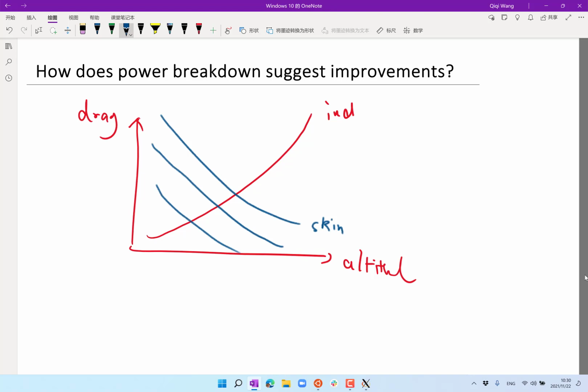There are two penalties. One is a weight penalty. So that's going to be the equation we supply to you. If you decrease the chord length, you get the wing smaller, but the smaller wing is actually going to be heavier. So that's something we probably want to start considering this week: as you keep your span and change your chord length, how is that going to change your weight?